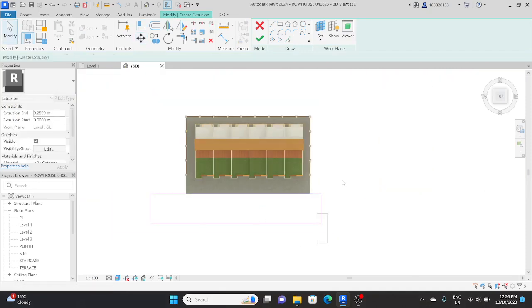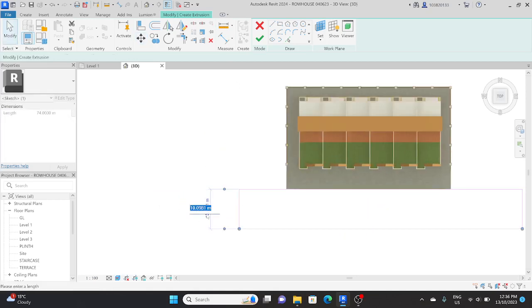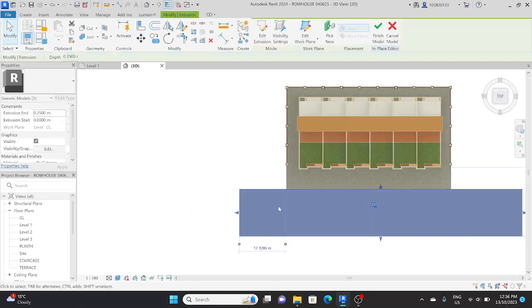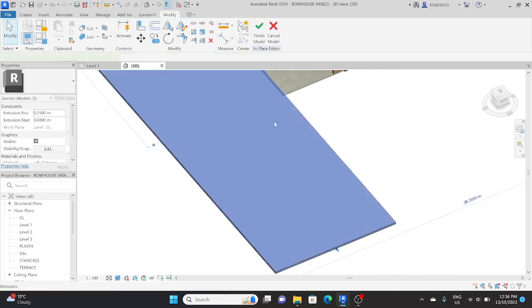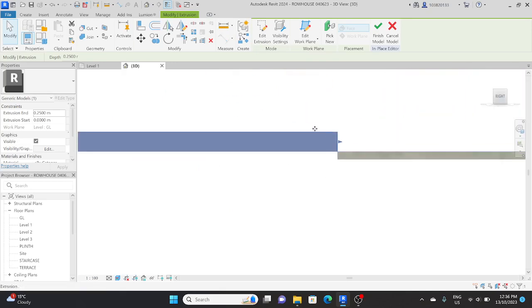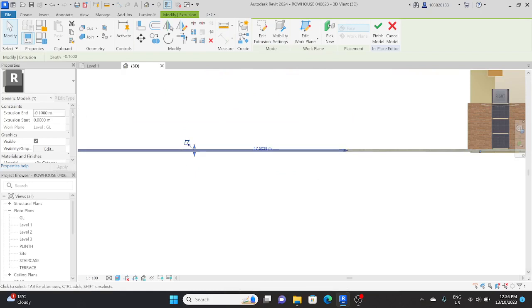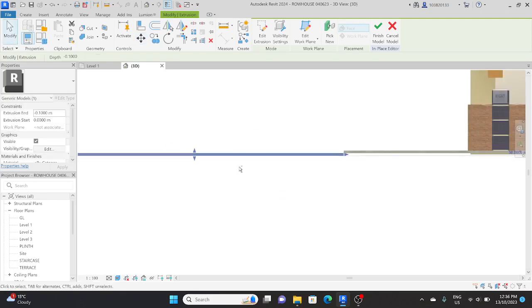Alright, so as you can see, I have simply made the road a random road, say about 12 meter, and now I'll select OK. So in this I'll just give a width, depth to my road, so it will be in minus 0.10 for example, and I want it to be below this, so I'll disassociate and I'll just simply move the plane below.